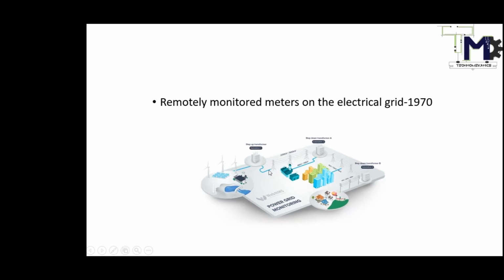Then it goes to the main distribution line, and again to substation 2, where we step down the electric current, and we send 66 kV to the industry which needs high power. Then again we step down, and it goes as 440 volts to the other substation, that is substation 3, and then it is transmitted to our house.